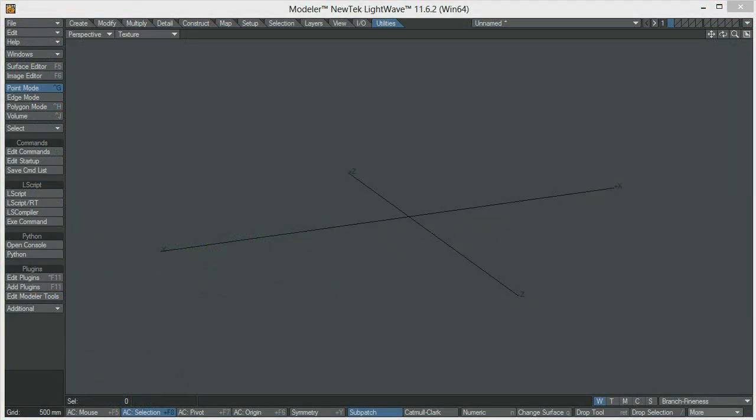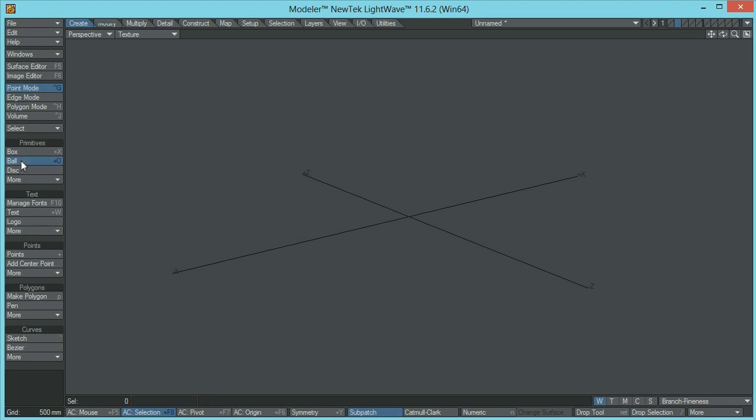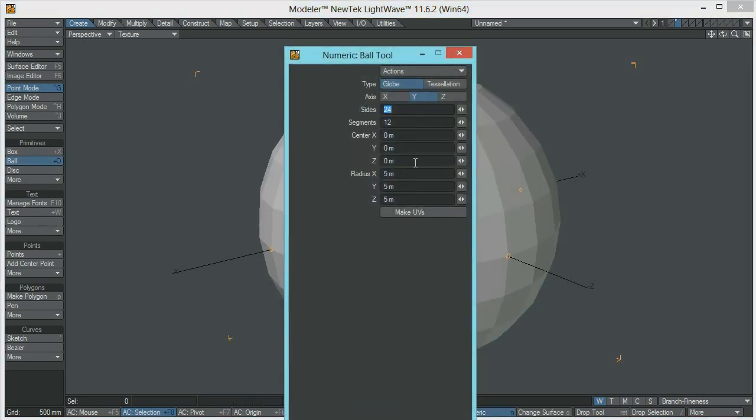Alright, so we're back in Modeler, and now we're going to create the trees using the DP Verdure plugin we just downloaded. The DP Verdure plugin works in a specific way, and I know it's going to be a little bit confusing at the beginning, but I just need you to follow the steps. So let's go to the second layer and let's create a big sphere. So I just created a 5-meter sphere.